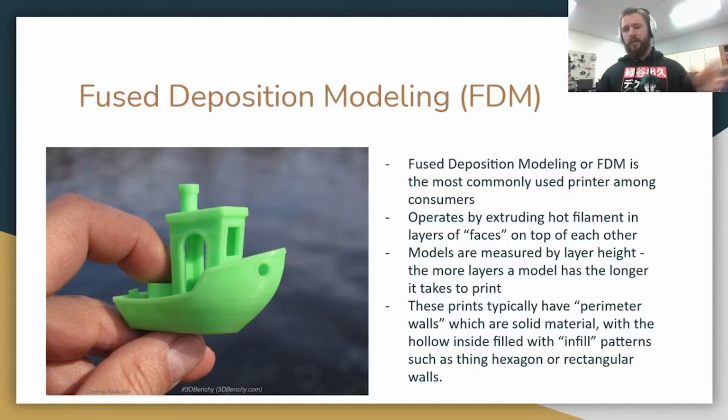You would probably go through a roll of filament every time you go to print something of considerable size. You can also use other infill patterns. I had a cube somewhere that was halfway finished that are kind of like honeycomb shaped, or rectilinear, which I think is just really long rectangular lines. All of these are different options that you can explore in your slicing software.